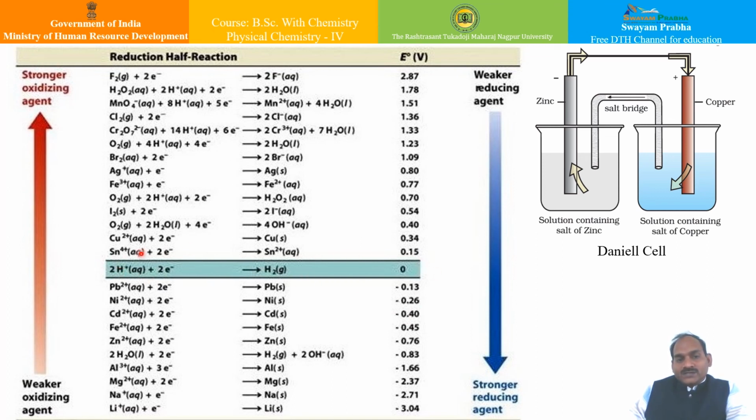There are many questions in corrosion chemistry, or in corrosion thermodynamics, where we can get answers to our fundamental questions: why you can have a brass screw on these steel sheets, which two metals can be connected with each other, or which two metals should not be connected in direct contact with each other whenever they are present in aqueous contact.